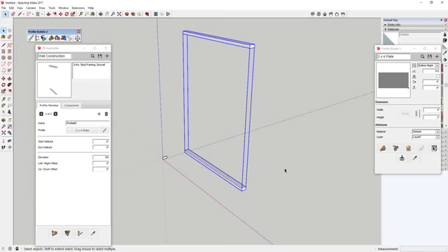If you select any assemblies that are in here, there's this little button down at the bottom that says apply assembly attributes. When you click on it, it updates your assembly to the new assembly. So now I've got a base plate and two top plates in here, so I have 3 profiles. We'll just call this top plate number 2, and we're good to go.